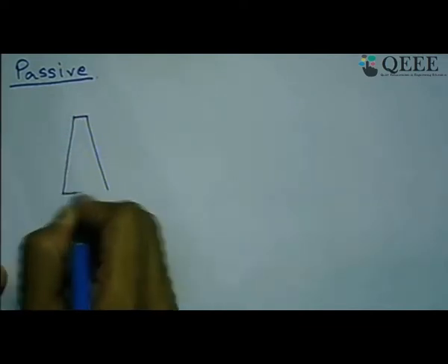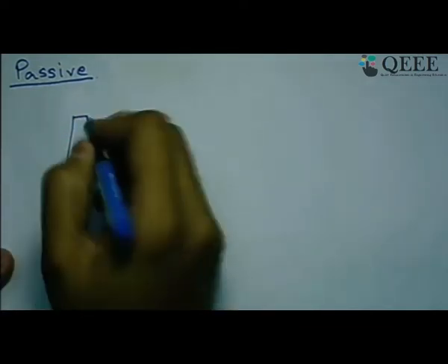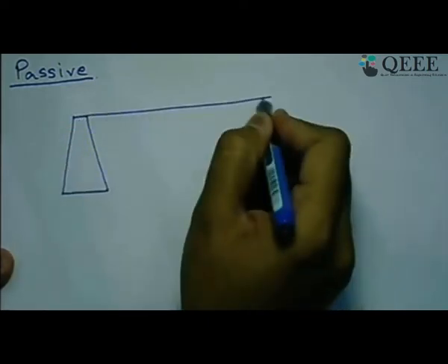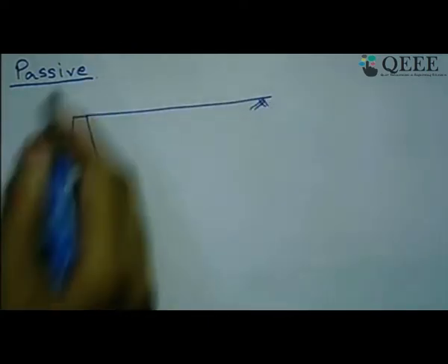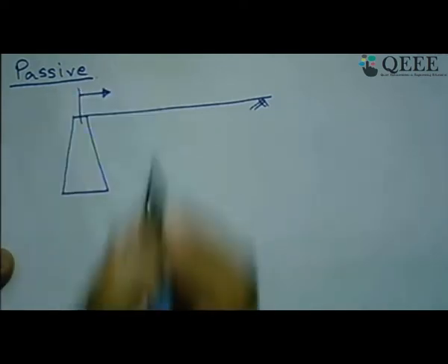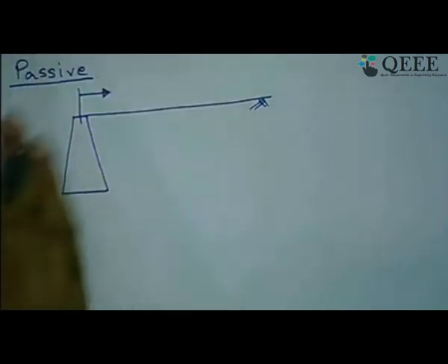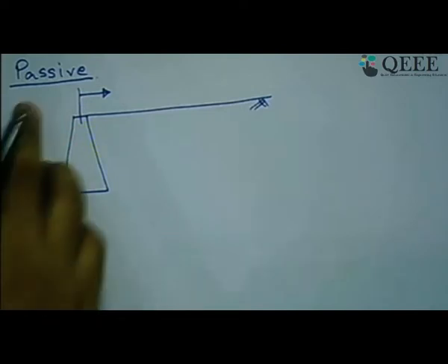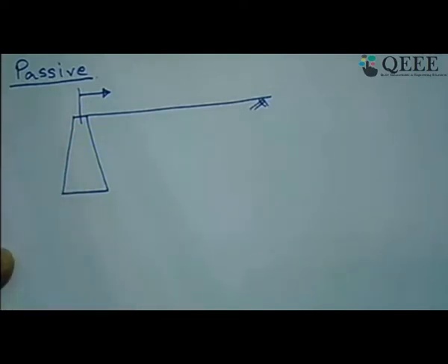Similarly, for the passive earth pressure problem, let us see what happens. So for the case of passive earth pressure, typically, or the more generalized case, first let me draw. So rigid retaining wall. Now we have backfill soil here. As I am telling passive, that gets decided based on how lateral movement of the wall occurs. Either it is sliding in this direction or rotating towards the backfill. That gets decided what state of earth pressure it is having. So it is passive state.